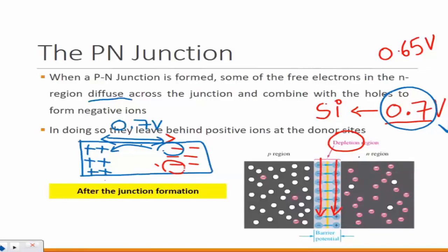So they have the capability to handle 400 volts without breaking. But there is always some limit, and we will discuss that as well, which is called the PIV rating of the diodes. If you apply too much, you will damage it. It's the same as any component for that matter, right?